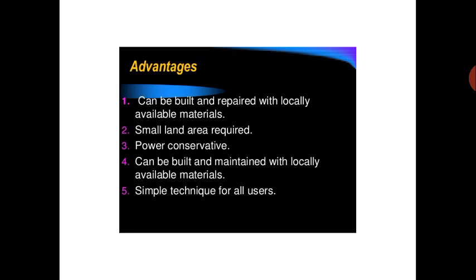Then, what are the advantages of this soak pit? It can be built and repaired with locally available materials. Small land areas are required. It is power conservative, of course; no power is required.